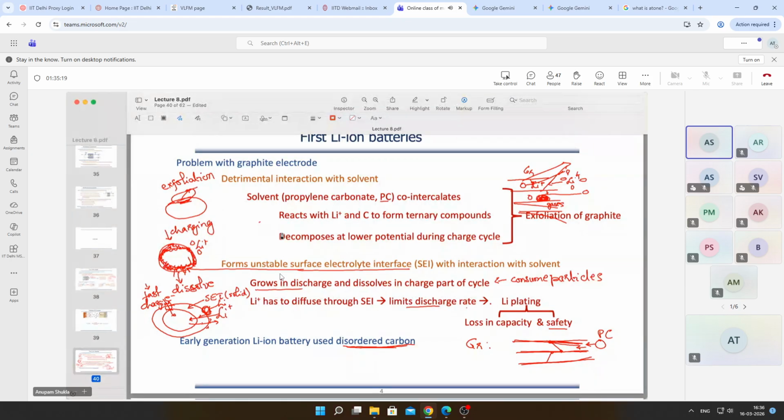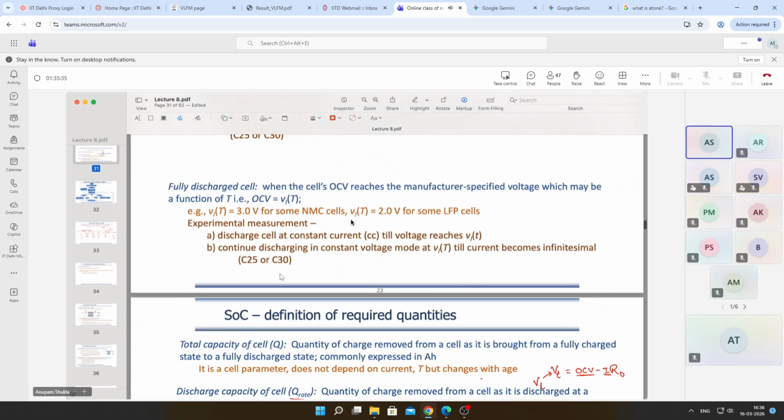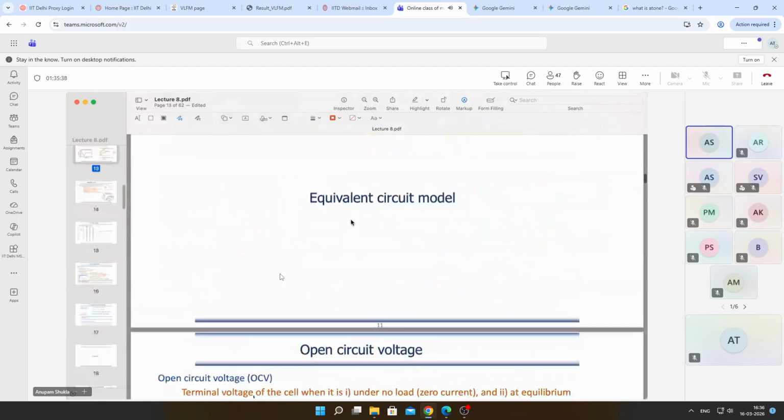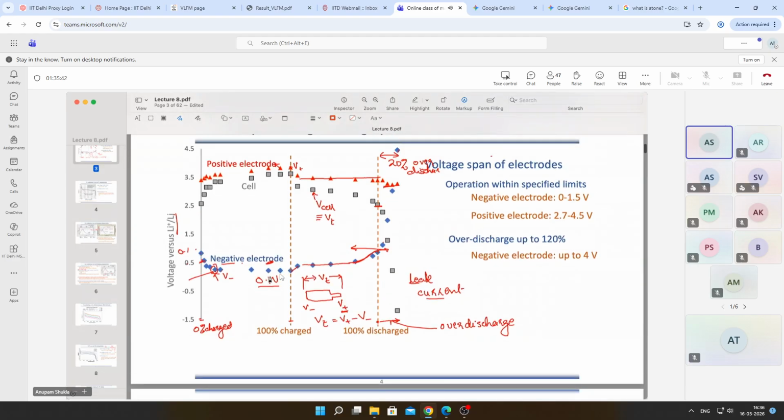Okay. And when the voltage becomes lower, they will continue. So when you start charging, remember when you start with a discharged battery, the potential of the negative electrode is a little higher. As we have shown, when we consider the discharge, that is why we have a lower cutoff potential. So remember the negative electrode potential when the battery is fully discharged.